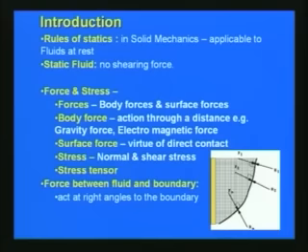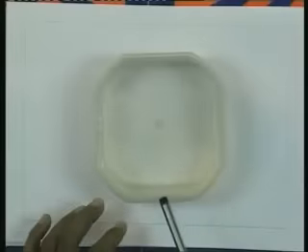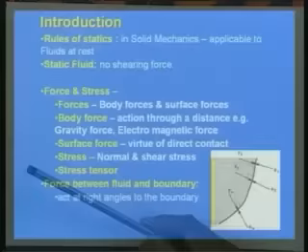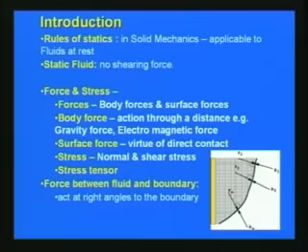And the second kind of force is called the surface force. Surface force is due to the virtue of direct contact between the molecules. So, what is happening as far as the fluid is concerned here? If you apply a force on the fluid, then due to direct contact between the fluid molecules only, there is a force. That force is called the surface force. And as far as stress is concerned, as we have discussed earlier, we can classify stresses as normal stresses and shear stresses. Normal stress means when we are considering a direct normal force on the body.